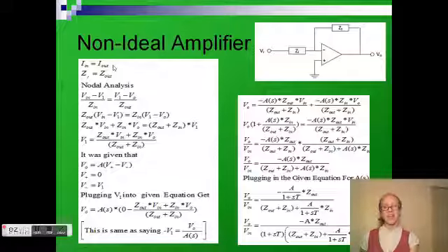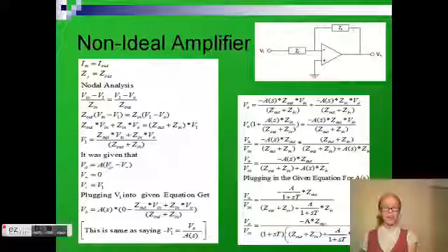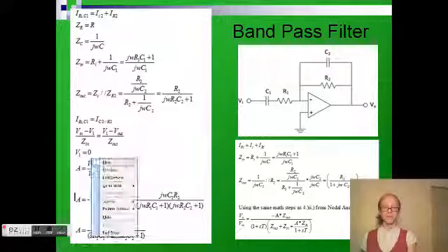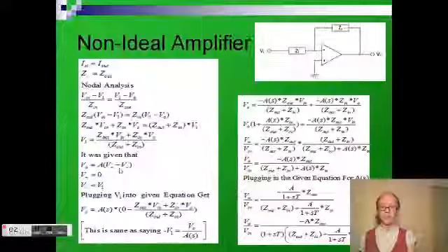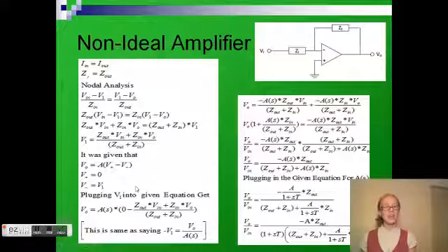So, if you were struggling at all through this math, you go through and you do the normal nodal analysis, and then you divide them over, as this should all explain, and then you use the given equation that V out equals A times V plus minus V minus. We know that V plus is for sure 0 in this case, but V minus is now our V1. So we take our simplified equation for V1 here and plug it in and continue.